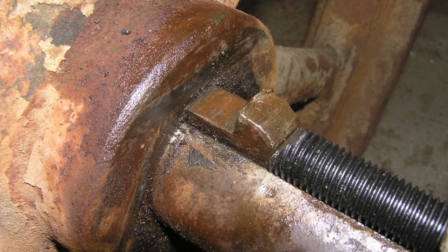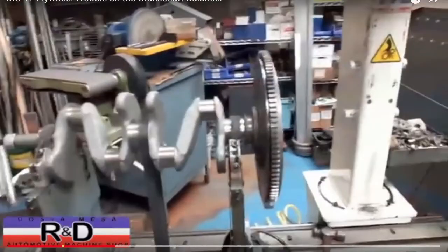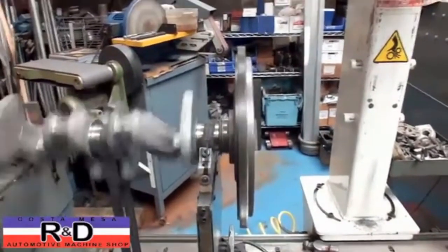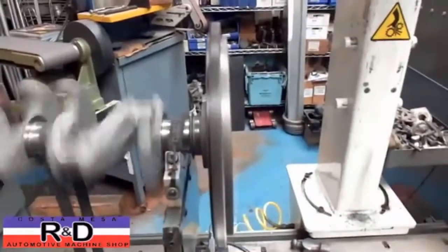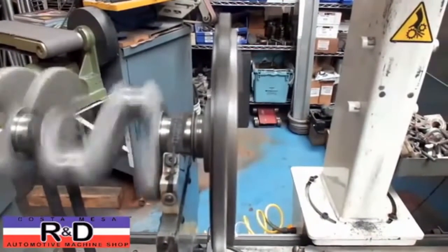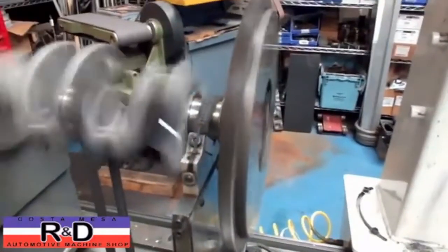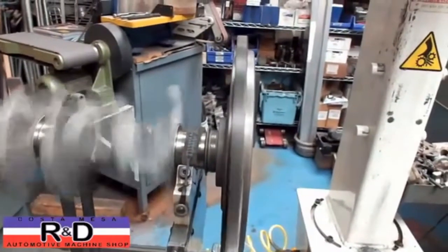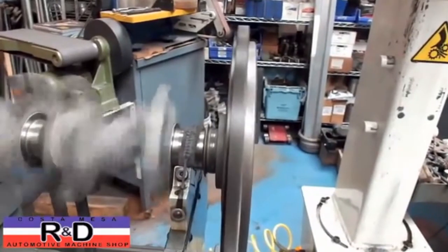One way a flywheel itself could fail is through wobble. Wobble is when the mass of a flywheel is not even across the entire symmetrical plane. This causes one part of the flywheel to be heavier than another, creating an uneven rotation. This uneven rotation can lead to major stability problems at certain speeds.